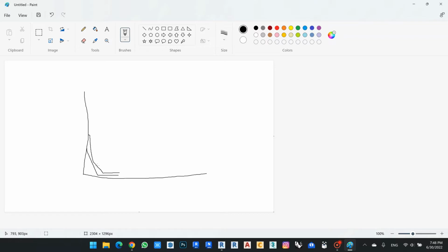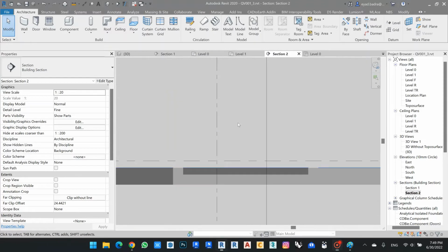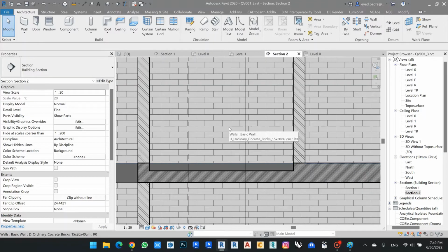After this, I have, let me say, the concrete stone or a screed or whatever, as a layer, and then the other layer will be my sand, and then my mortar, and then my ceramic. This is the level of the finish, and after this, the other level of the finish with the mortar and the other ceramic of the wall. So we can make a quick implementation of what we said now.